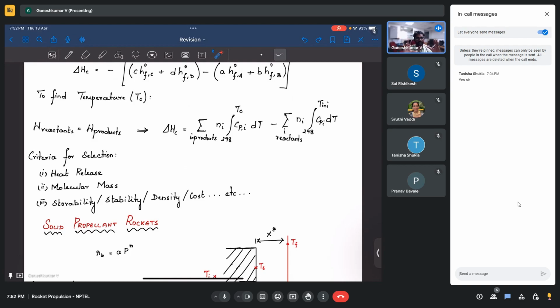Now, on the product side, this gets opposite. So formation enthalpy reduces, and whatever the formation enthalpy difference was, it gets added as sensible enthalpy. Sensible enthalpy is something we feel, and we measure it using temperature. So that's why the temperature of the gases goes up.